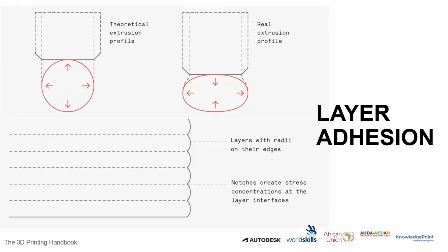To achieve this, the filament is pressed against the previous parts, pressed down, and the hot extruder end reheats and melts previously printed layers. The downward force and partial reheating of the underlying material enable the bonding of the new layer with the previously printed layer. So this is like the adhesion, but you also need to understand how this really affects your profile,